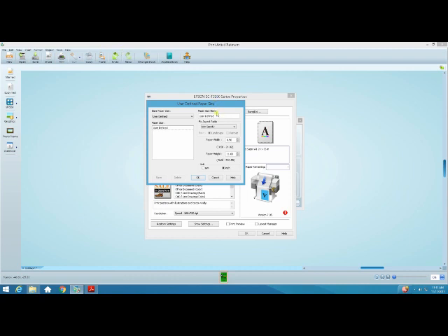So what I'll do is I'm going to go into this. I'm going to say, look, I want to create something that's 24 by 36 and I want to save that size. And what I'm going to do is change it right here. And you can see this is going to be the paper width and this is going to be the paper height. The paper height in essence is indeterminate, or it's determined by the original length that you put in. So in this case, maybe 150 feet or 100 feet. So we're going to change this, and we're going to make this 24, and we're going to make this 36. Okay? Now, we have millimeters or we have inches. We want inches. We're going to save. And look, there it is.